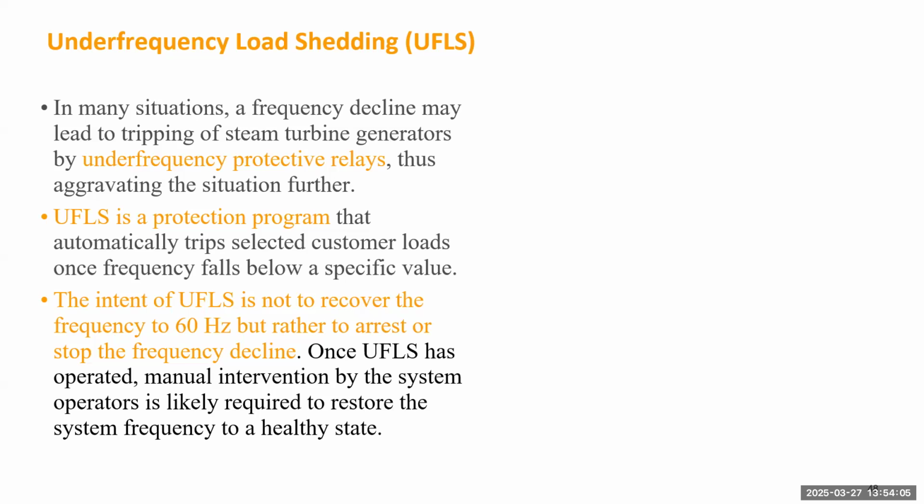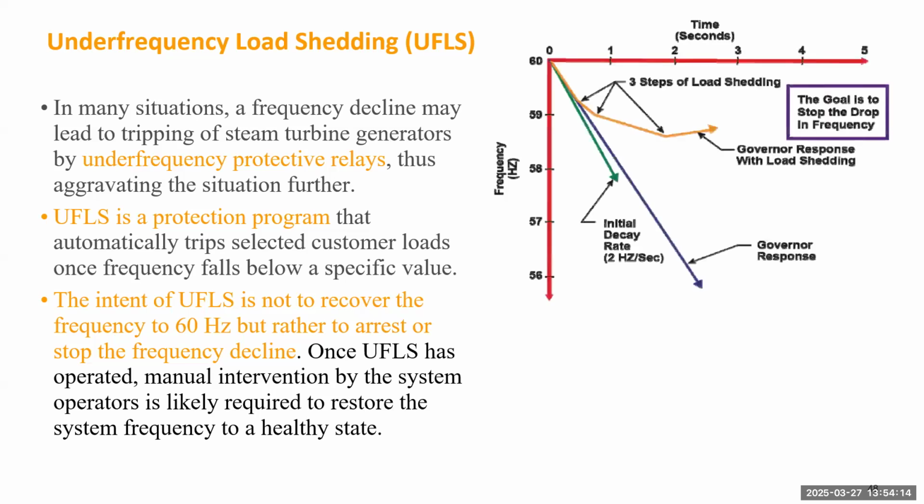Such that you can avoid very low frequency. The control is sometimes based on the offline design, and you can have, for example, 3 steps. Most schemes shed load based on the slope of the frequency decline and also the real-time frequency, for instance using the formula we proved in earlier slides.